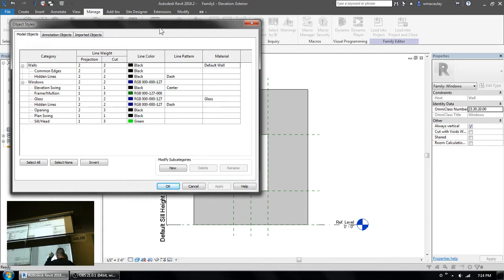Now, what happens if I decide that I'm going to make the glass really heavy too? Same line weight, so a fairly thick line weight, like maybe 0.35 millimeters for my frame and my glass. Maybe makes the glass a bit heavy. So I'm just telling you this from my experience. I like to see a fairly heavy line weight for my frame, and then a slightly lighter line weight for the glass, just so it doesn't become too blobby in the window. So for my frame, I might have a line weight of, say, 3.